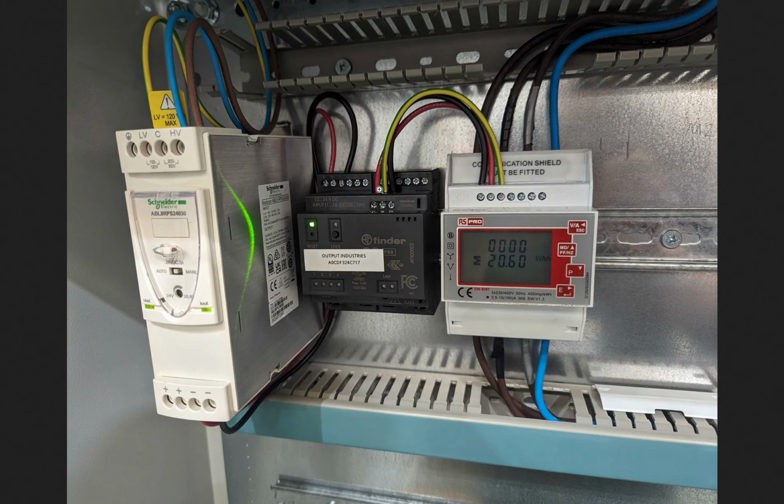So using the Modbus protocol here, we have a 3-phase power monitor. This is giving very granular information on, obviously, energy usage, but it's also giving us very granular information on each of the phases. So voltage, amps, power factor, things like that is all being captured by this device at a very high frequency. We're passing this over to, again, our data acquisition unit. This data acquisition unit is then wirelessly transmitting that information back to Busroot. So it's doing double duty.